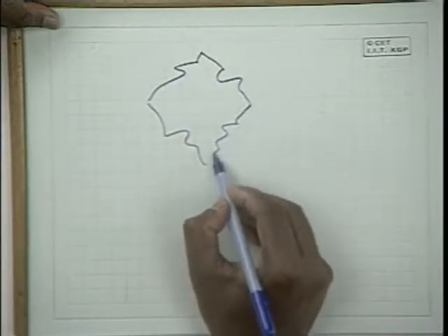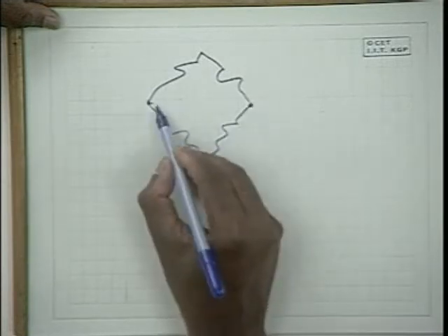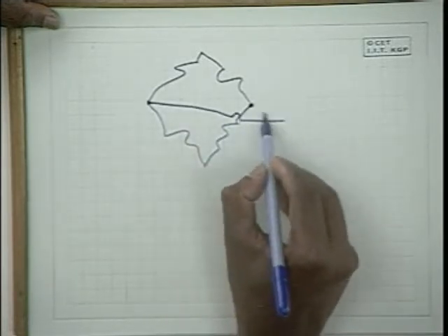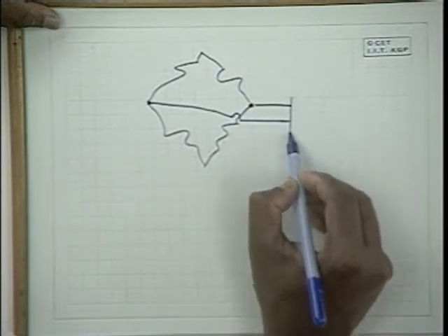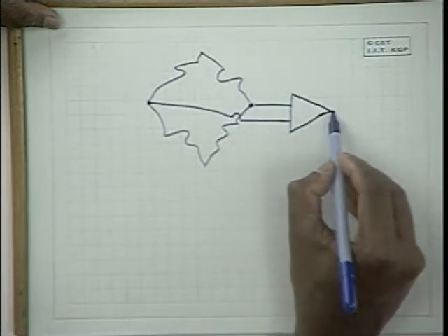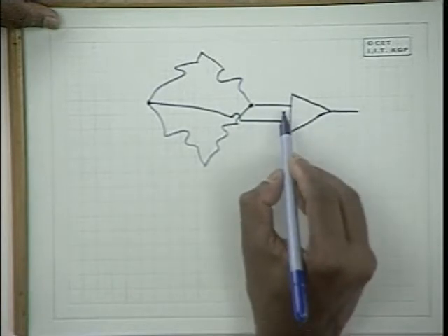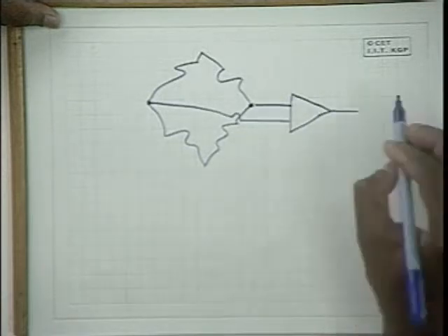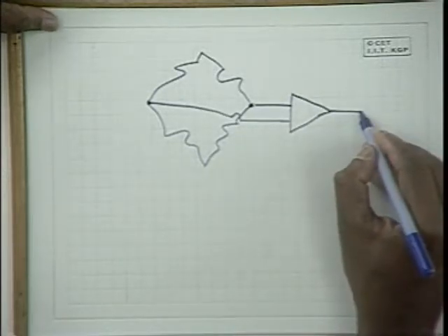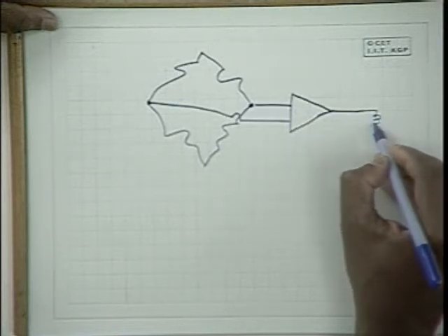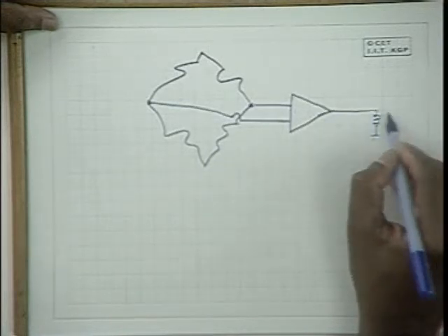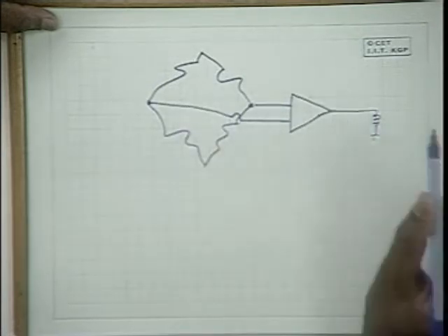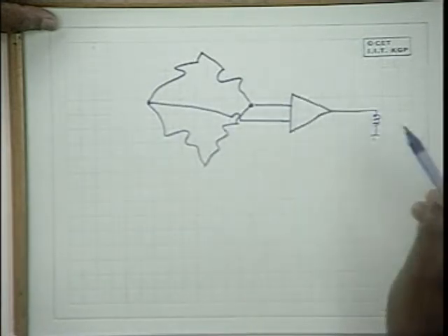So there, both the inputs, for example, in a bridge circuit like this, to determine the null between these two, we tap both the outputs and we amplify it using a difference amplifier. And even if there is a small amount of difference, this amplifier amplifies that difference and gives you a substantial output. Now this can be given to an indicator where the indicator indicates the amount of difference signal, with amplification, of course.